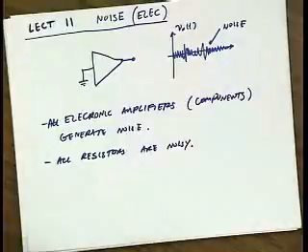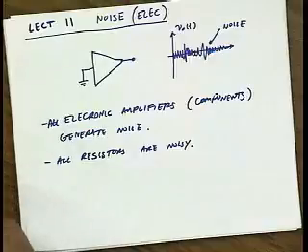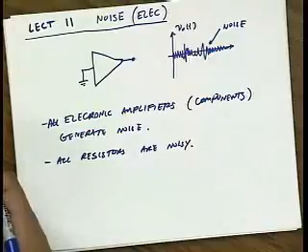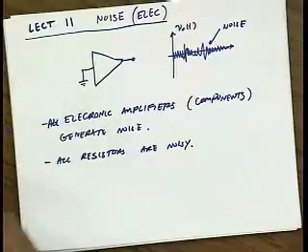If you think back to how a resistor works, you can imagine where this noise comes from. Remember, in our simple model for a resistor, you apply a voltage or an electric field and you get drift current. In reality, though, you have drift current as a small contribution to a large fluctuating current.